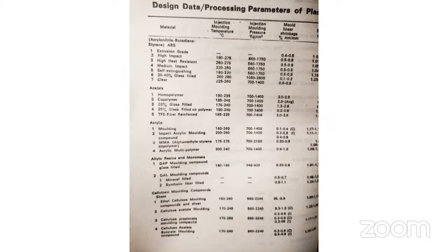Yes. Actually, some six shots can be there inside the barrel. In general, there is a terminology in our industry, but is it 6 shots or is it based on something else? Because barrel size also plays a role: 32 dia barrel or 36 dia barrel or 25 dia barrel. Yeah, the barrel size is also very important, but not only the barrel, the whole screw and barrel assembly will also play a very important role, because how the flights are arranged, what type of screw you are using, single stage, double stage.